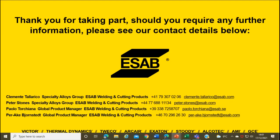I go to the second one. What is the smallest plate thickness in electroslag welding cladding? Maybe Paolo? Yes, thank you, Clemente. It depends, of course, a bit on the welding process, whether it's going to be sub-arc or electroslag, and the strip width going to be used, but in general, it has to be above 30 or 40 millimeters, because the heat input will distort the base material. Absolutely. The size and the energy make a big effect in that regard.